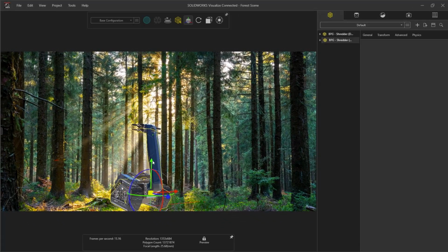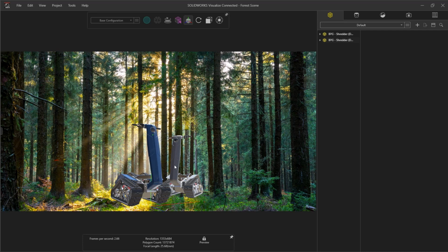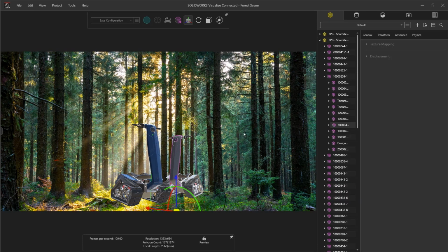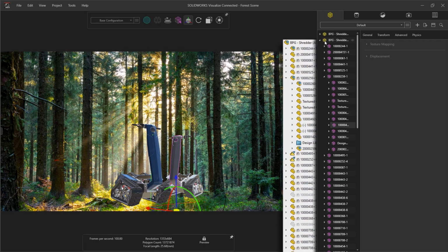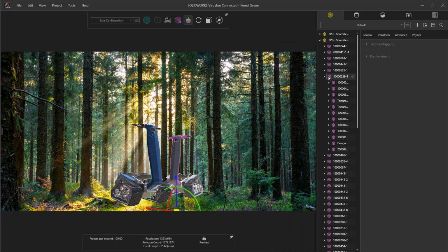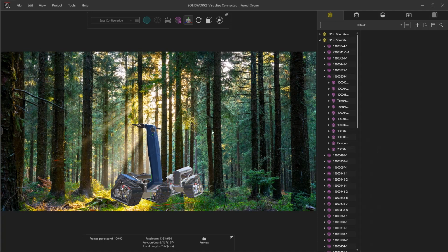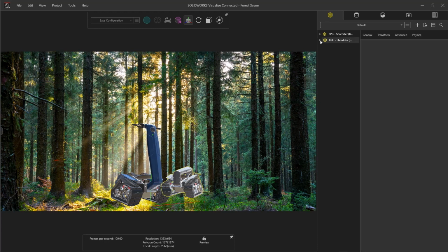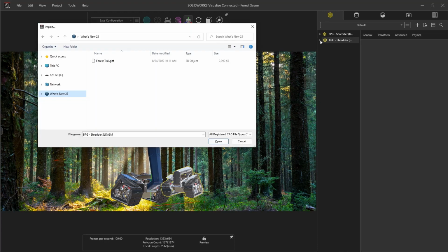The component, part, body option works in a similar fashion to the automatic mode of past releases, but has been updated for this release with one important distinction. This import option now mimics the SOLIDWORKS assembly structure whilst retaining appearance control in Visualize. This is an ideal situation as Visualize users can take better advantage of groupings such as sub-assemblies already defined in the SOLIDWORKS model. Putting your designs in context can go a long way in immersing your viewer in your world.